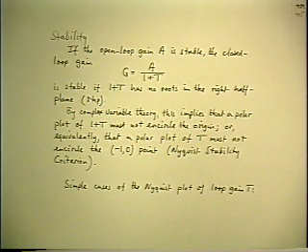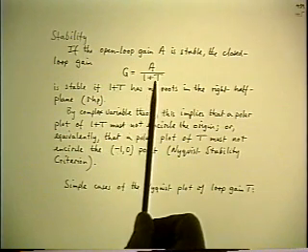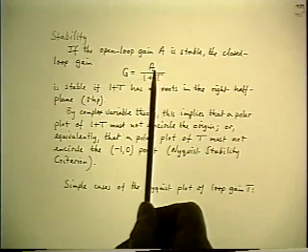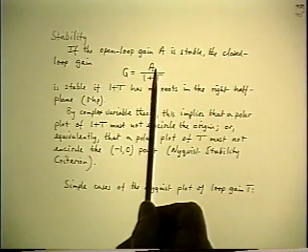For example, even inside each transistor, that collector-base capacitance is in a feedback position. And there may be other internal feedback loops that are unintentional, but you're stuck with them anyway. So in fact, it does require a separate independent assumption that the open loop amplifier itself is stable.